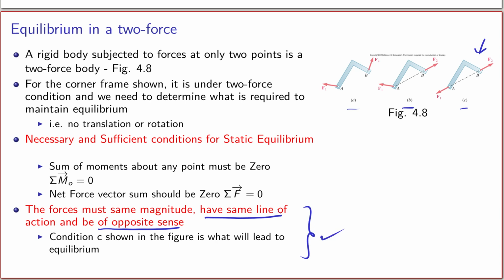Okay, so just keep this in mind, because when you start solving complex problems that involve members or parts which are subject to two forces, like shown here, or forces only act at 2 points, as shown here, then you can immediately realize that in order for that to be in equilibrium, the forces need to be behaving in this manner shown in figure C here.